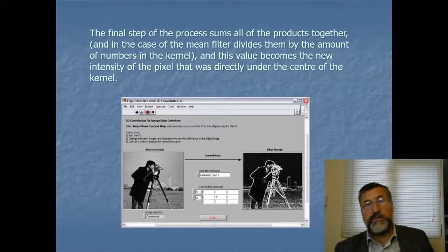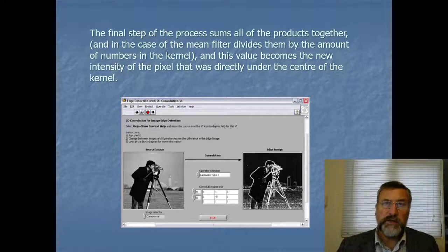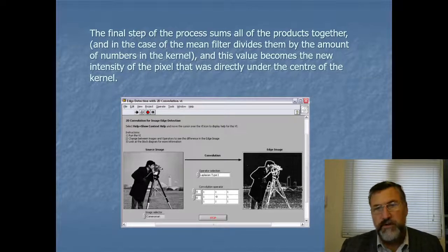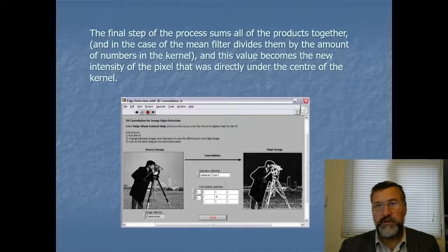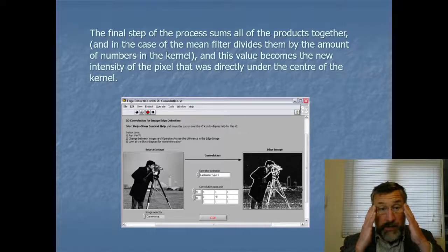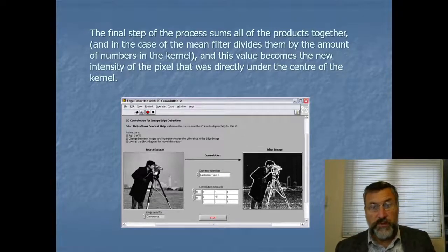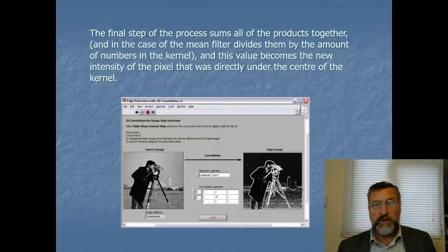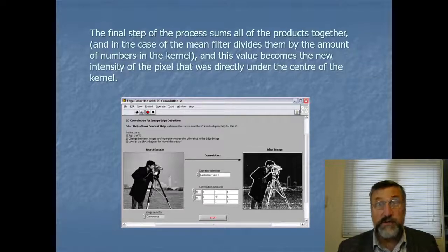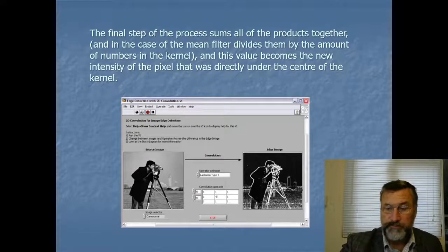Because what you're trying to do in machine vision is reduce the data a lot of the time. In traditional classical machine vision, you take an image, it's a grayscale image, there's loads and loads of information in it, the computer can't interpret. Well, not unless you use deep learning or something. You simplify it by thresholding it, so you just turn it into a monochrome image, black and white, which is less data, and then you apply an edge filter if you've got an object you're trying to measure in there, so all you're interested in is the edges. You're reducing the data again, and then you can just measure that distance across the top of the box, say.